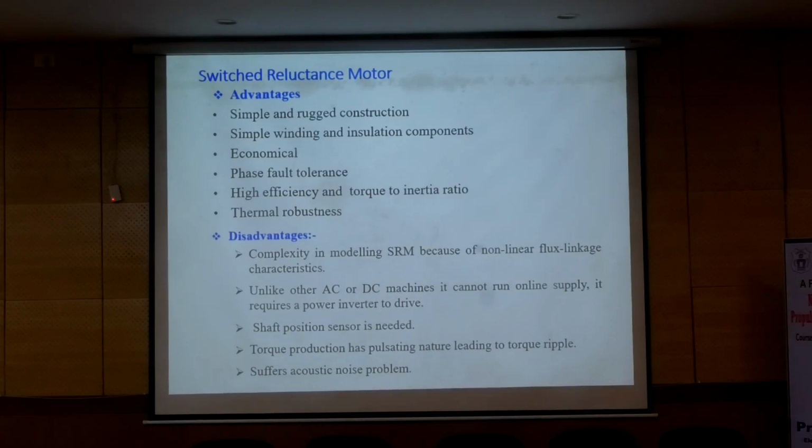So because of this, the motor is limited to very few applications at present. But if we minimize this torque ripple and hence the noise, this motor becomes more apt and more advisable for a large variety of applications, wide applications in fact, because now we are talking about the EV machine, electric vehicles.